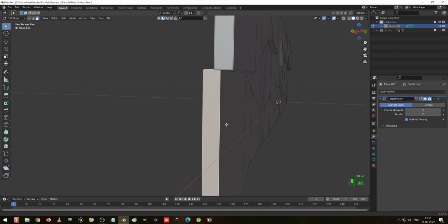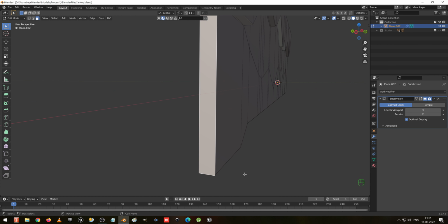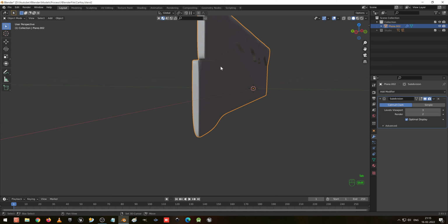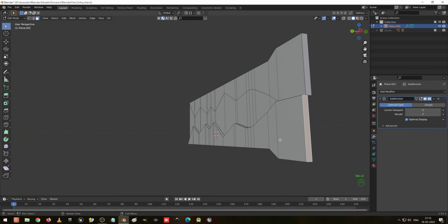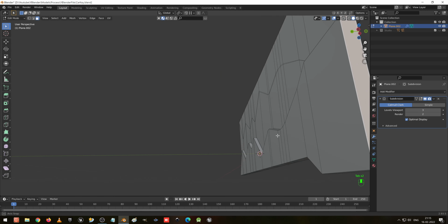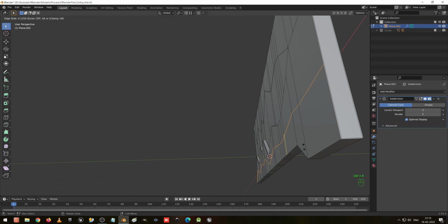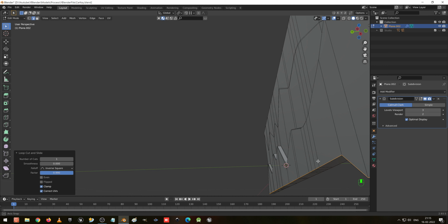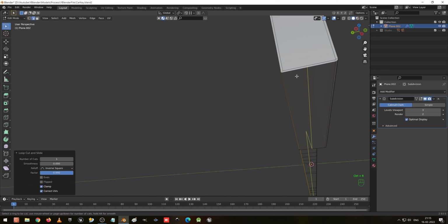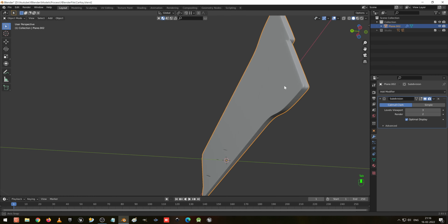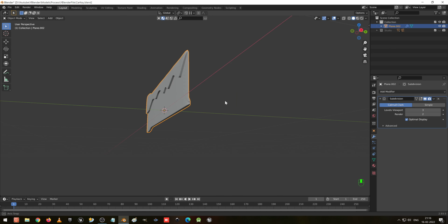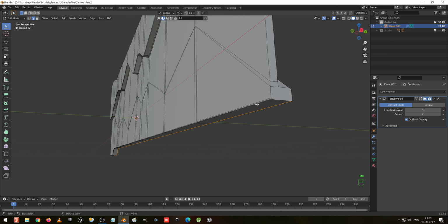This also I press I to insert and create a small edge loop here to make the shape better. And this corner too, I am adding a corner to make this edge sharper, and I add one more corner for this to make this sharper. So the key shape has come out perfectly for us.